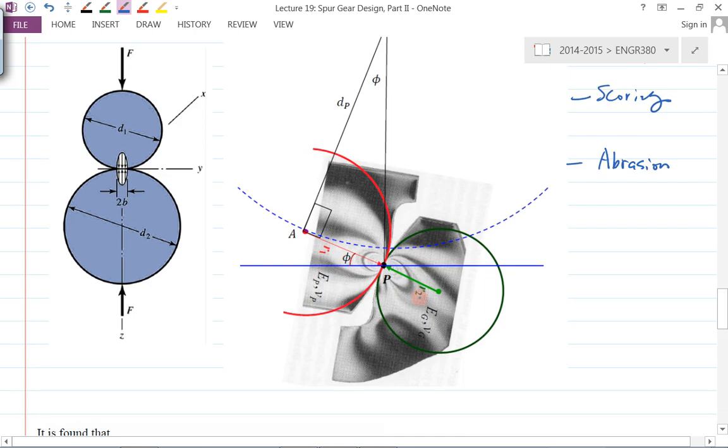This is the gears in contact with each other. Okay, yeah. Through much evidence, the first sign of wear always appears on the pitch line here. Okay, on the pitch line, basically somewhere in the middle of the gear tooth, essentially. All right, yeah, that's the first sign.